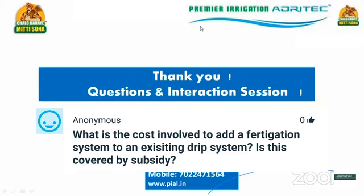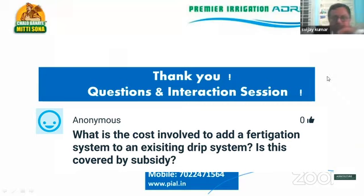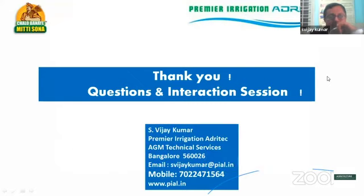What is the cost involved to add a fertigation system to an existing drip system? Is this covered by subsidy? It will not be covered by subsidy if you are putting it later, and the cost of adding a complete unit may be in the range of 8,000 rupees. But if you only want the Venturi and just the throttle valve arrangement, I think it can be done within around 4,000 to 5,000 rupees. There are different sizes of the Venturi. If you're going for a small area, a 1-inch Venturi can be used, and then the cost can be even lower. Definitely we can do that.